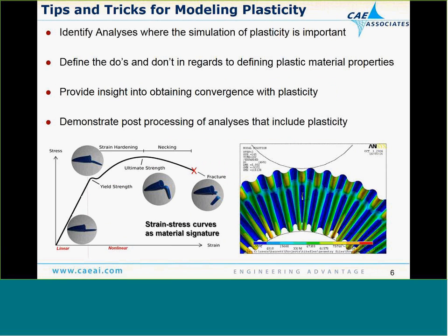So today's topic is tips and tricks for modeling plasticity. The items I'm going to cover are identifying analyses where simulation of plasticity might be important to you, do's and don'ts in terms of setting up your material properties, insight into obtaining convergence, and more information about how to evaluate your results from running a plastic analysis.